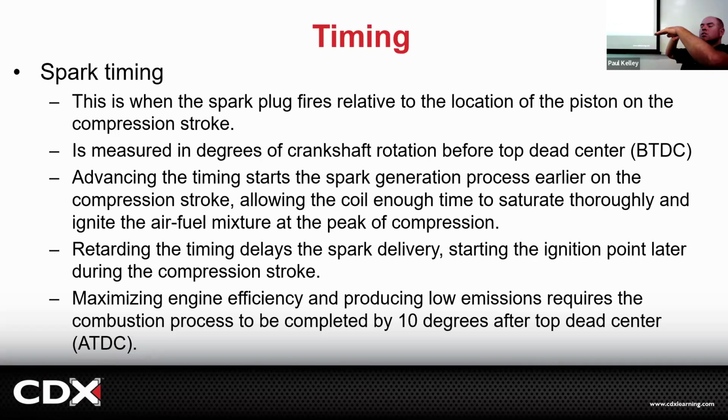You'd want to start extra early, maybe 20 degrees before TDC, because you want to get a good push on it and you're moving fast, right? So how many degrees before TDC? I don't know. The computer looks at a lot of things. But we do want to advance it more under heavy loads and under higher RPM. That's for sure. All right, so that's what timing is.